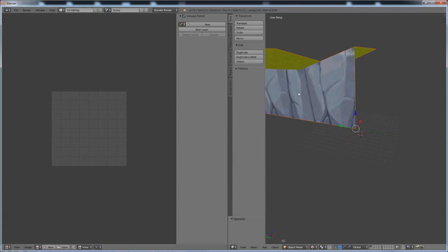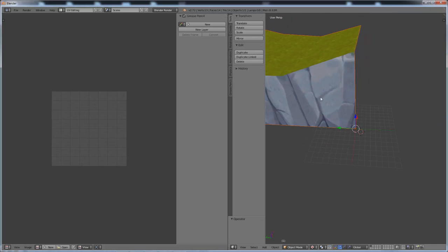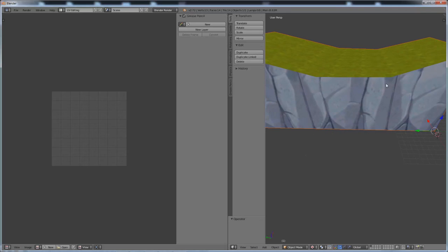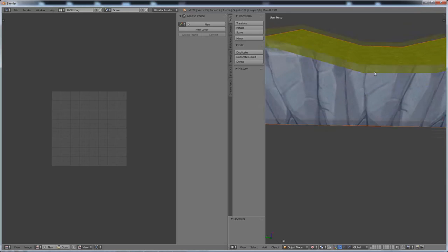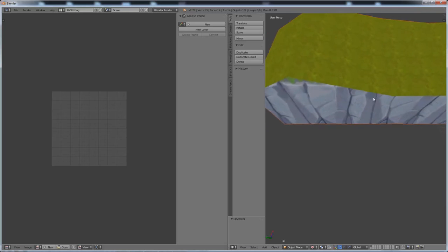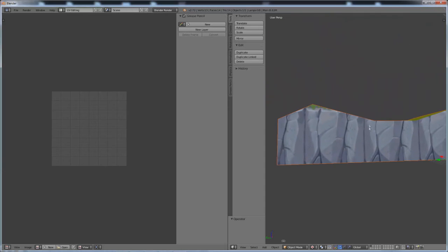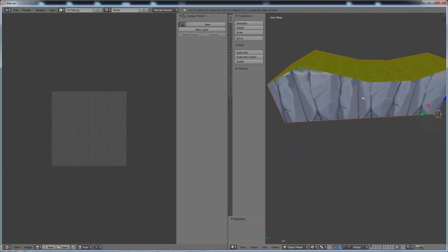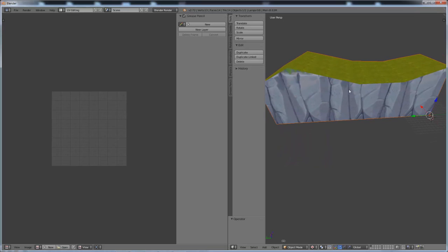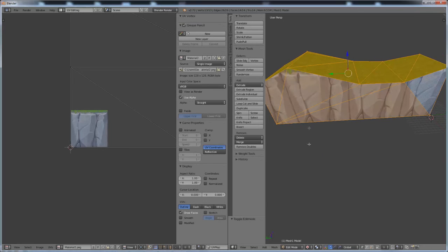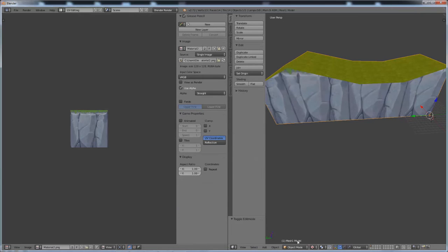Now, the camera controls are quite similar to SketchUp. You need the shift button though. It's pretty weird how the camera controls work sometimes. It always has something in the focus, and by shift you move where the focus is. Now if you right click this and press tab, you go into edit mode. You can switch between edit and object mode by pressing tab, like you see there.